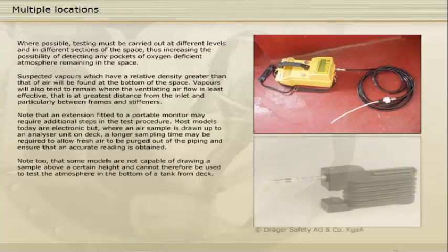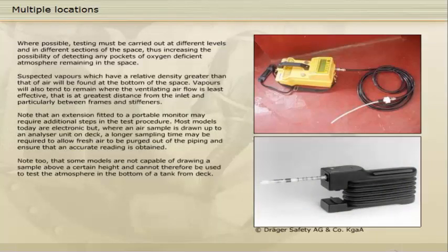Note too that some models are not capable of drawing a sample above a certain height and cannot therefore be used to test the atmosphere in the bottom of a tank from deck.